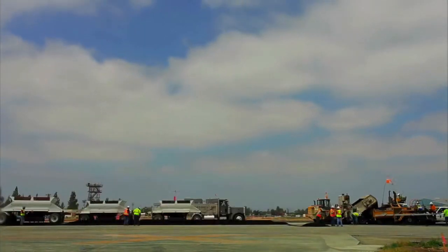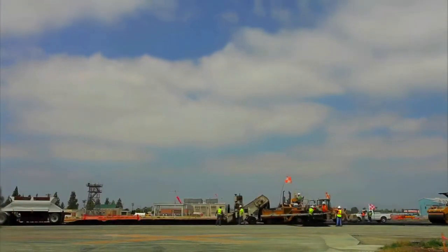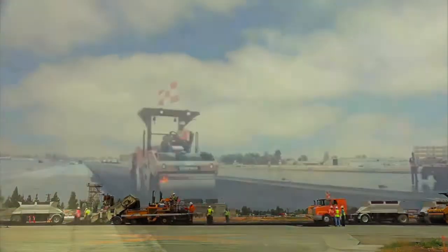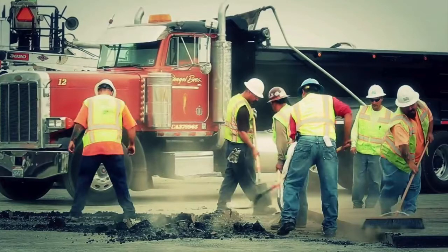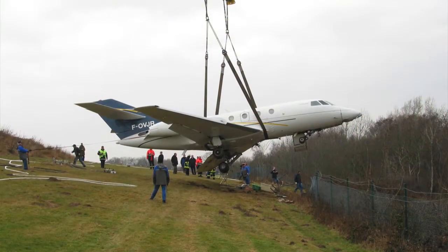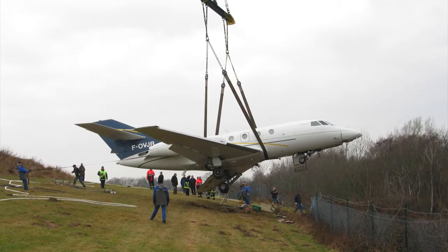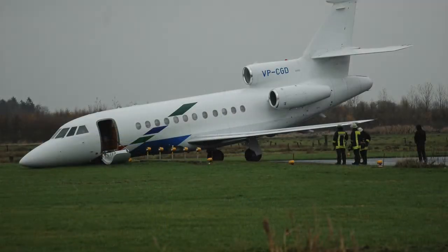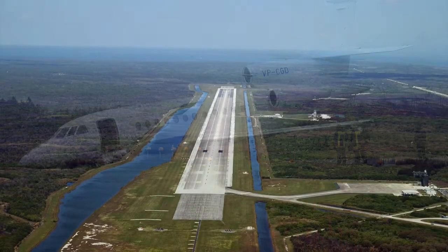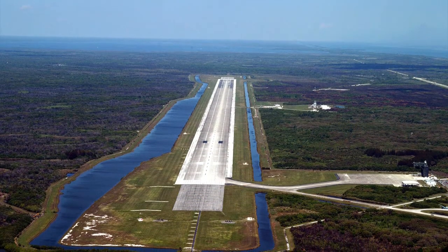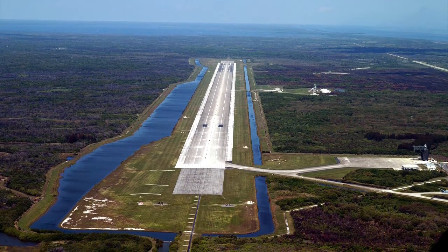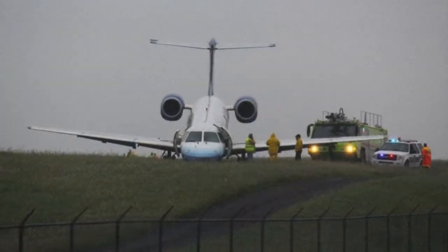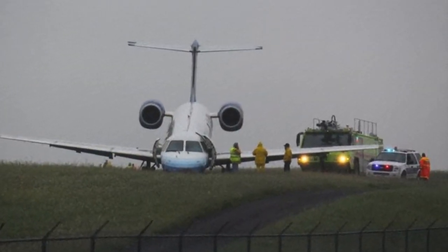areas. Runway safety areas, usually referred to as RSAs, are based on accident statistics about overrun and excursion events. For example, the majority of aircraft involved in overruns come to rest within 1,000 feet of the runway. Consequently, the RSA program requires that all Part 139 airports establish 1,000 feet of RSA beyond the end of the runway. This 1,000-foot safety area doesn't have to be paved, but it does have to be level, drained, and graded to support the weight of a typical aircraft and emergency vehicles in the event of an overrun.